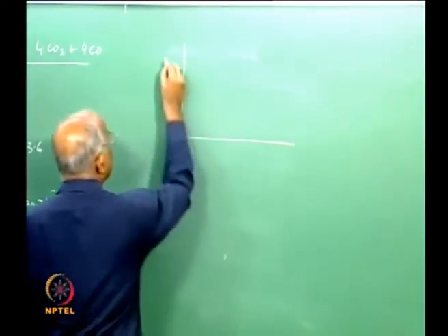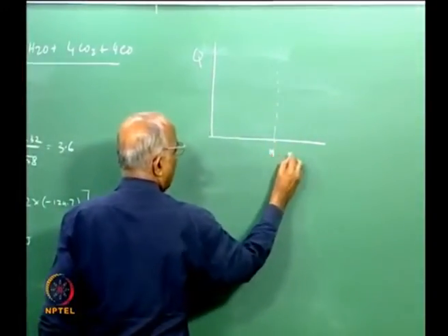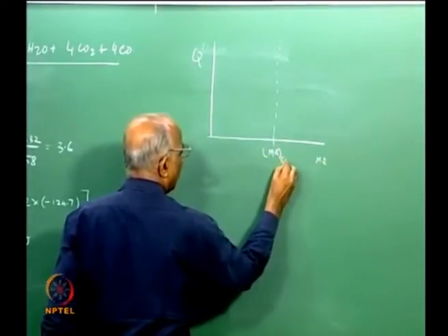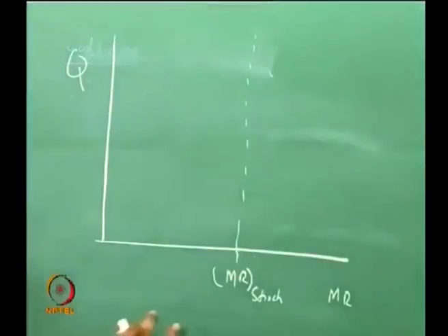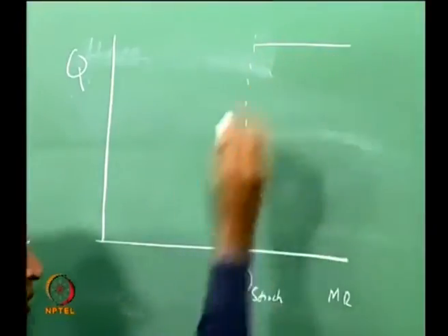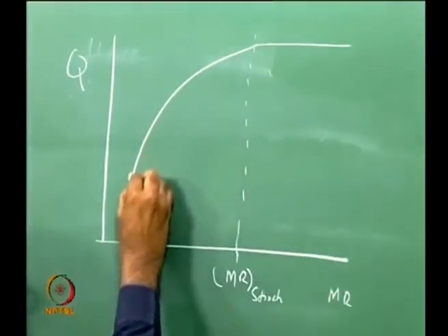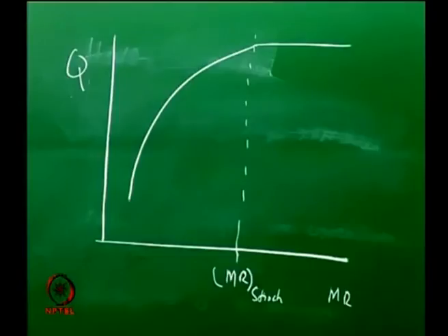I say, what is the heat release in a reaction. Suppose this is stoichiometry, I plot it as a function of mixture ratio, and this value I call mixture ratio stoichiometry. I find anything more than this gives me the maximum value of heat release, whereas below this I keep on dropping because unoxidized or not completely oxidized products of combustion are being formed. Is it all right? Now I want to convert it into temperature. How will I convert it to temperature?